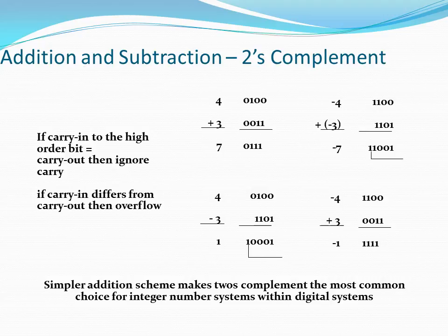One thing to remember: for any combination, if there is any negative number, before performing the addition operation we represent the negative number in signed 2's complement, and then perform the addition. Whenever there is any carry, we discard it. That is the mechanism to perform addition by using signed 2's complement.